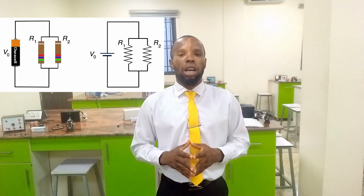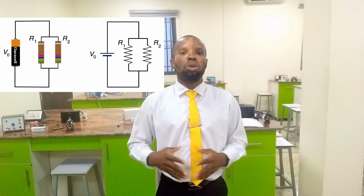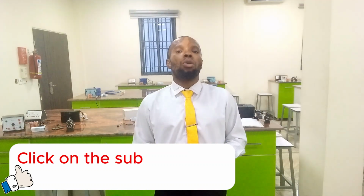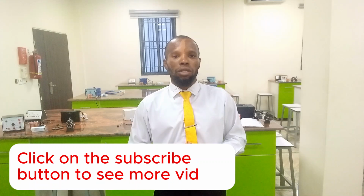In today's practical, we'll be using experimental procedures to verify the law of combination of resistance in series and also to verify the law of resistance in parallel. After that, we will do a graphical analysis that will show us, if we combine resistors in series and in parallel, what our combined resistance, also known as effective resistance, is going to be.